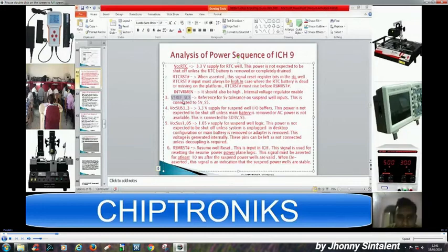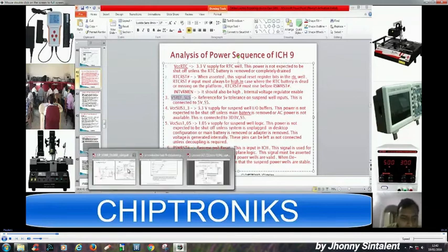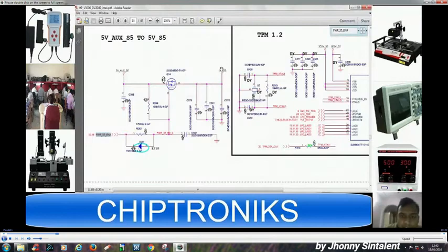So we have to check for the V5 reference sus, and for checking this, we have already seen this is connected to the 5V underscore S5, and you can see this 5V underscore S5 is coming from this 5 volt LDO output of the 3 volt 5 volt regulator IC, and it is becoming 5V-S5 via a MOSFET. And this is a P channel MOSFET.